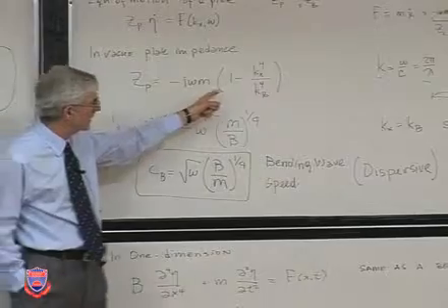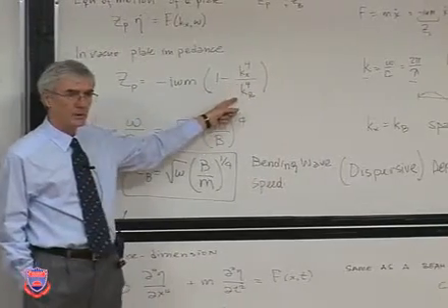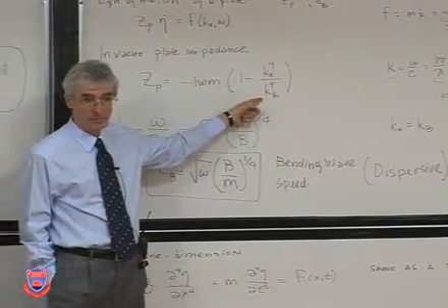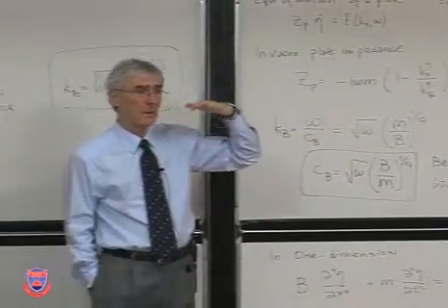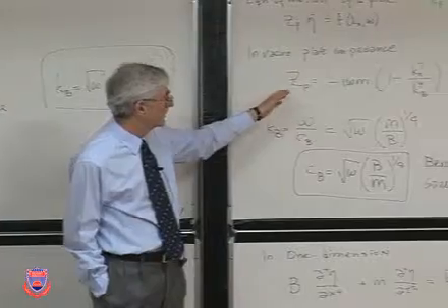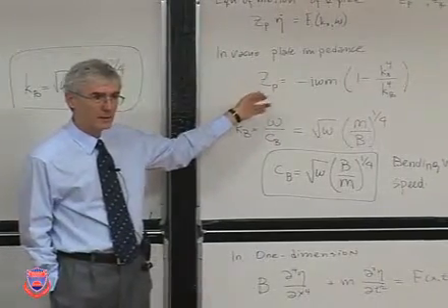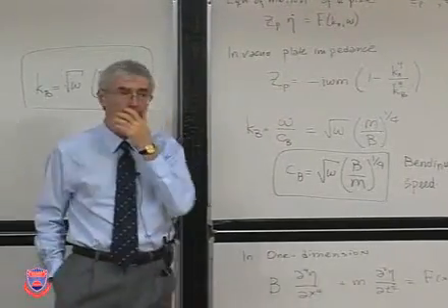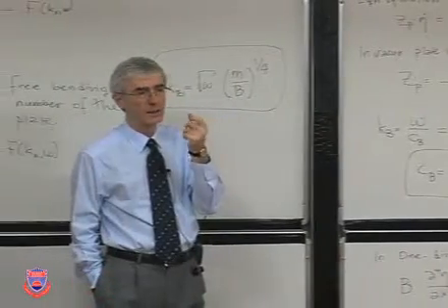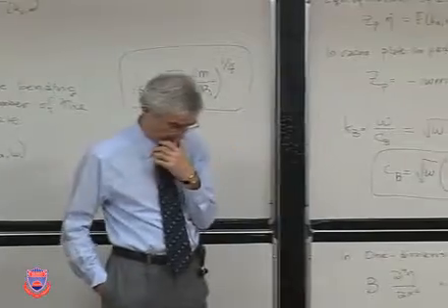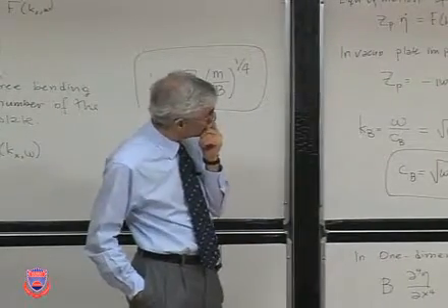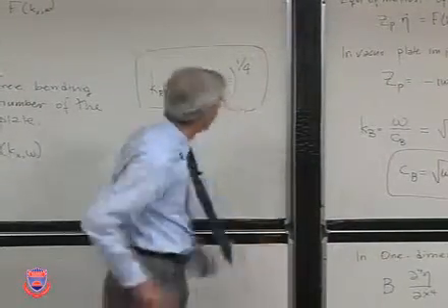Because we're saying here, if Kx is equal to Kb, then you have impedance going to 0, and so there's a spatial resonance. But there has to be damping in the system. Where would damping come from? Let's think about material damping, because that's what all the materials have. Effects of damping.